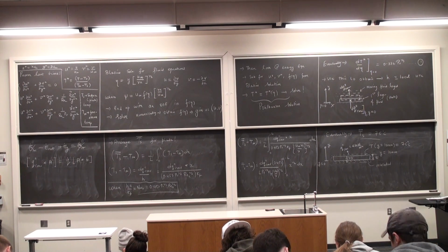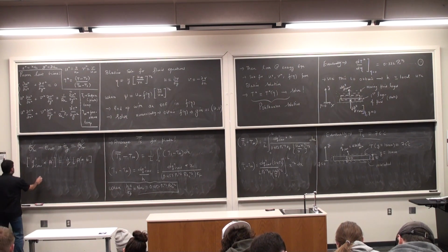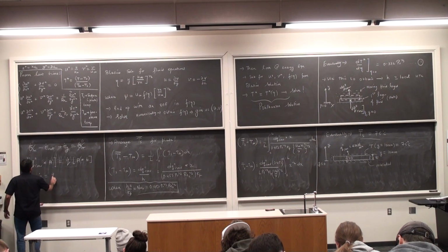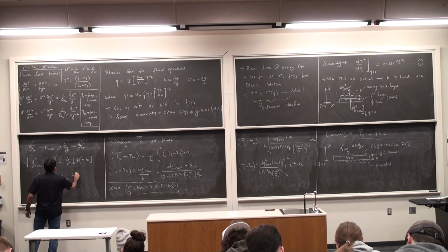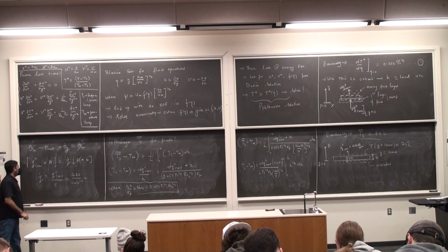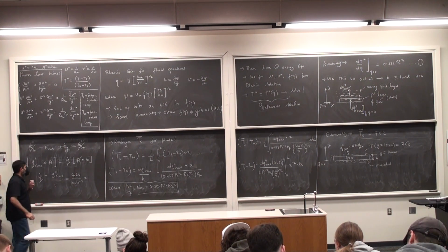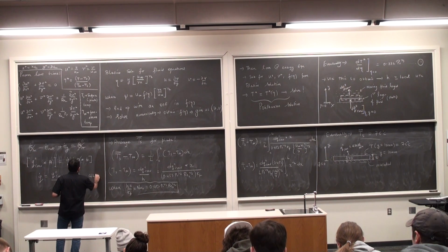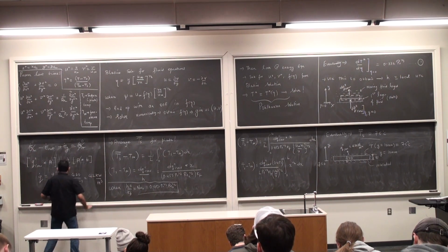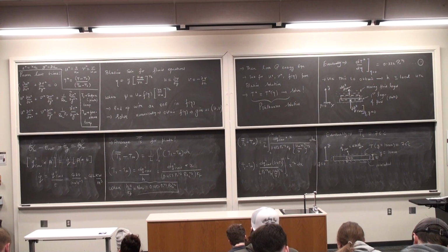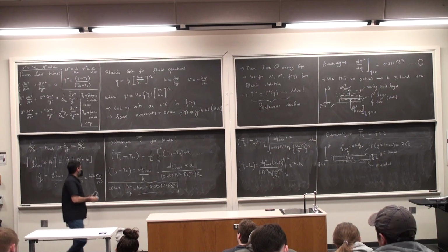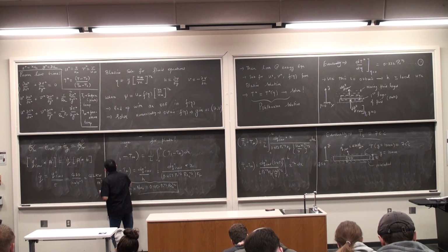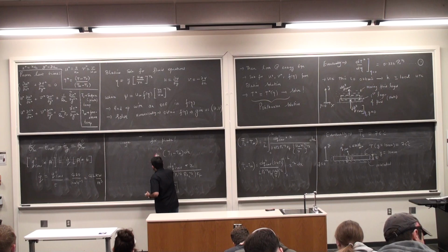Surface area cancels out, so that I have Q dot is Q double prime convection divided by the thickness, and that's 420 over 10 millimeters, which is 42 kilowatts per meter cube. This is now going back to the beginning of the semester, where you did this energy balance, you calculate Q convection and Q conduction and so on. And then the last step in this problem, I have 1 more minute left.